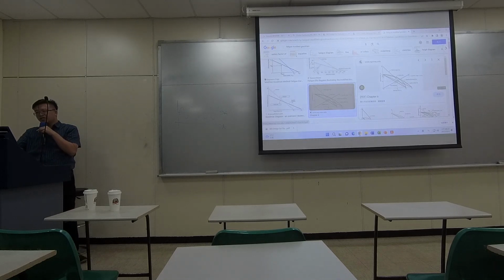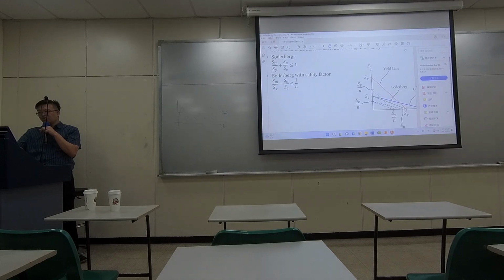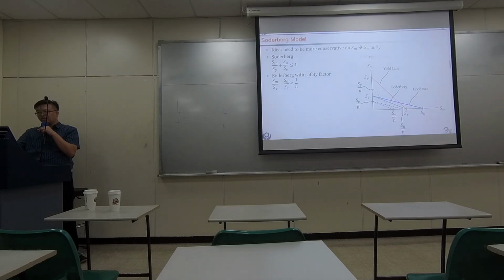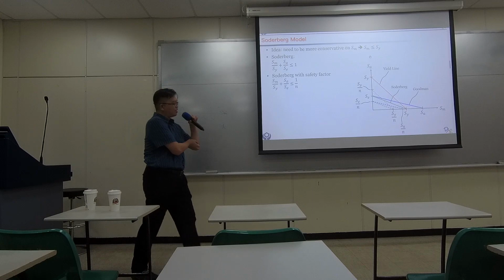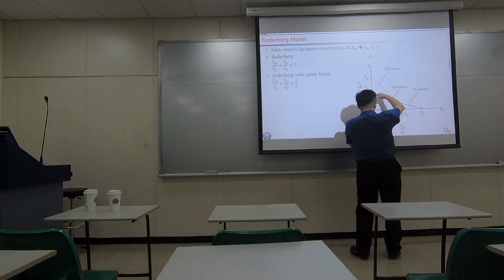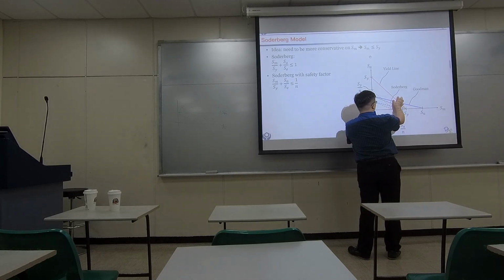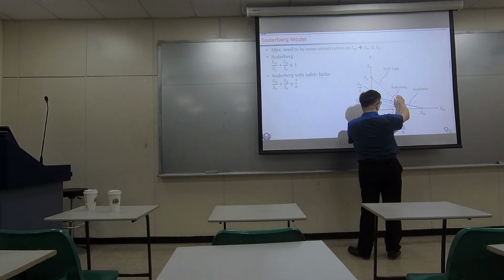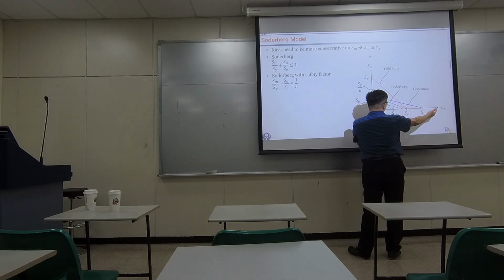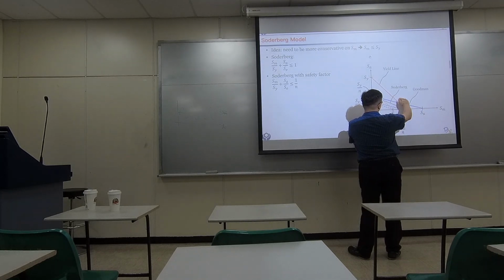Has an intersection with the same upper limit, but they don't believe you can only have a straight line for your design limit. So there are actually some other models that believe you can have more design space on the upper right area. So it allows you to have greater mean value and also greater amplitude.